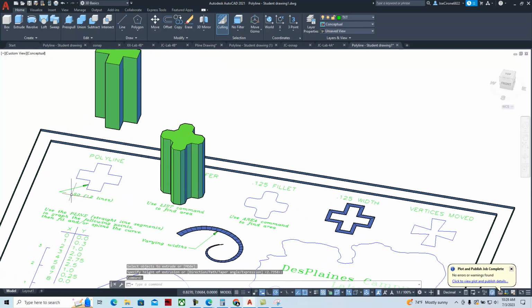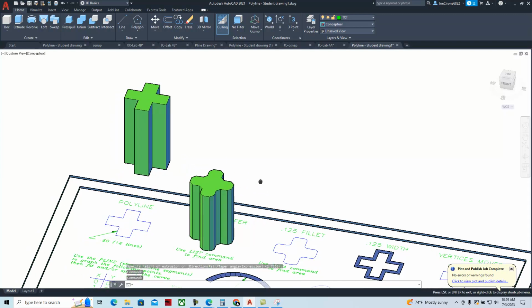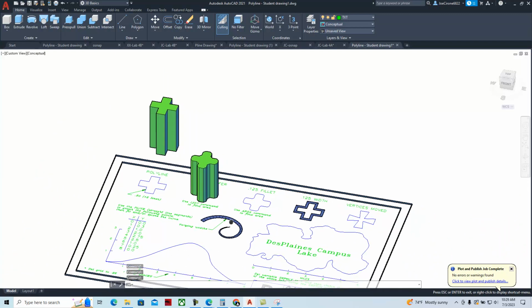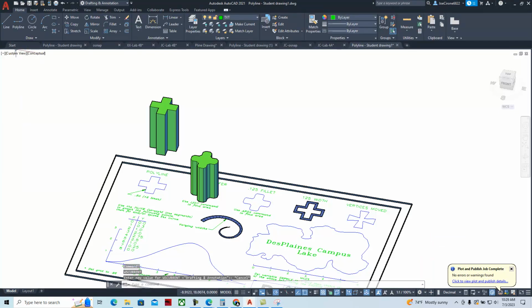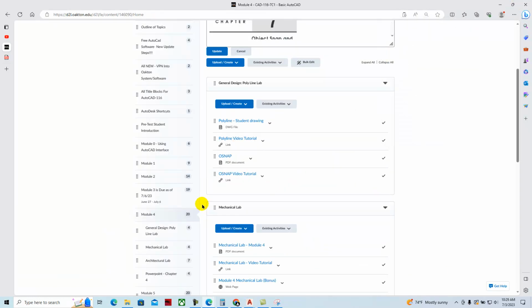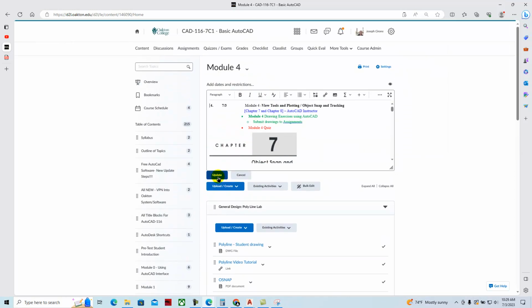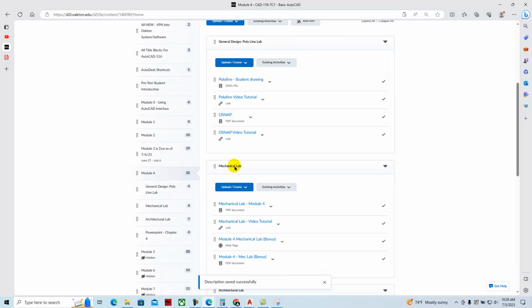And same with these other ones where we could extrude this shape. Shift middle mouse wheel. And then we have like volume that we can actually analyze and create different Boolean operations with them. So polygons are really quite powerful when we get down to working with 2D and 3D type work. Back to drafting and annotation, back to our 2D view, go to a top view. So we'll create these different polygon geometries in this exercise, and there are videos on how to do that. And so we have a polygon video that's located right here. You can select it.